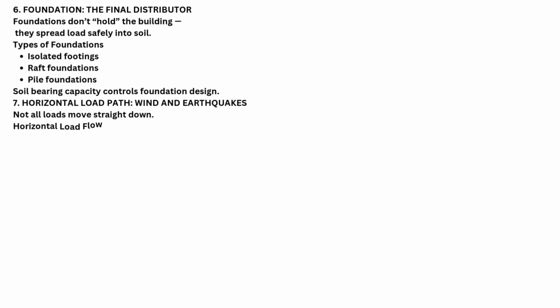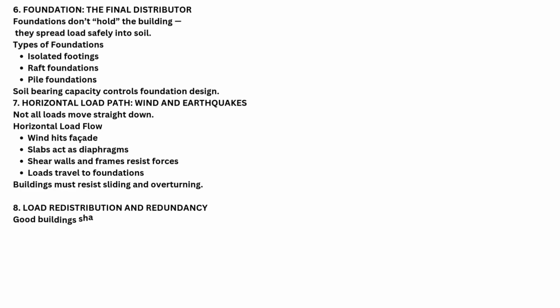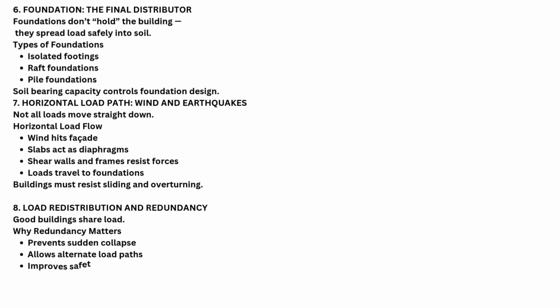7. Horizontal load path. Wind and earthquakes. Not all loads move straight down. Horizontal load flow. Wind hits the facade, slabs act as diaphragms, shear walls and frames resist forces, and loads travel to foundations. Buildings must resist sliding and overturning.